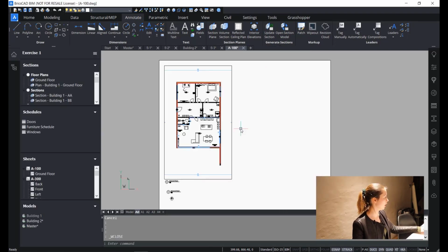And again, I will sum up what you can store. You can store title blocks, you can store layers in there, you can store colors that you imported, line types that you imported, hatch patterns that you imported, blocks that you created, text styles, dimension styles, and page setups. So basically a lot that you can specify. So certainly worth taking a look at if you want to customize your entire drawing process. A drawing template could be the solution for you.